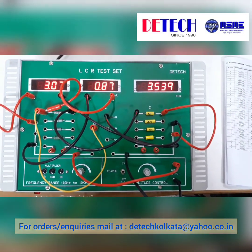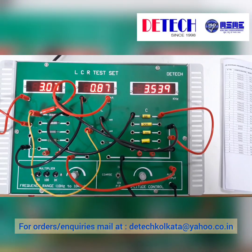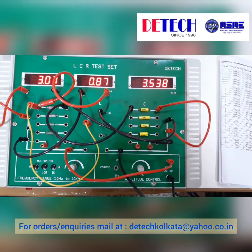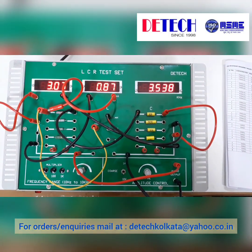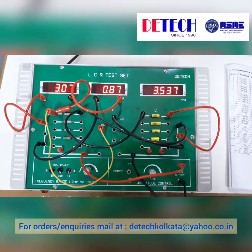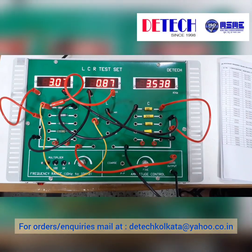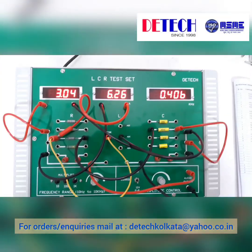If we do a theoretical calculation for the values of 220 ohms, 100 millihenry and 0.02 microfarad, then we will find the resonant frequency to be 3.4 kilohertz. So we are getting a very good value, which is almost equal to the theoretical calculation. We will now try out another combination.